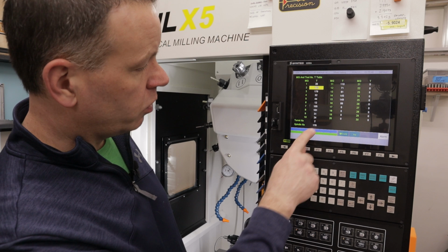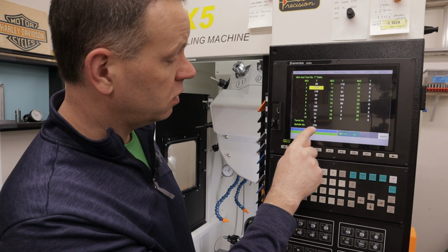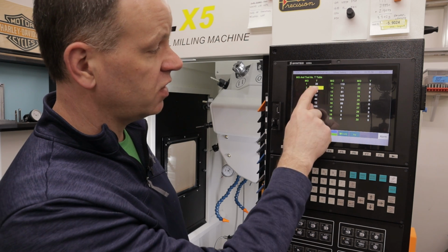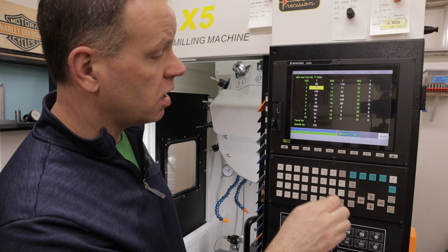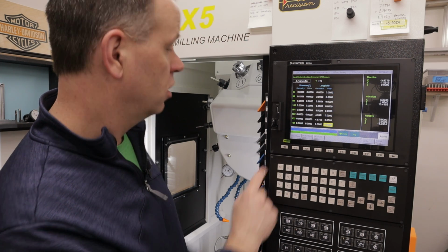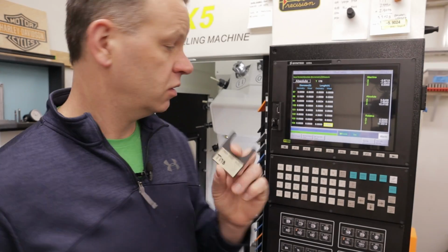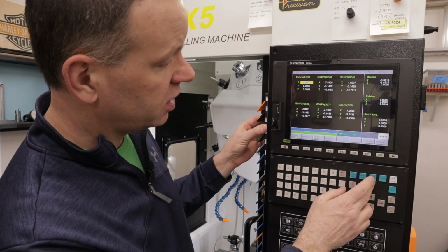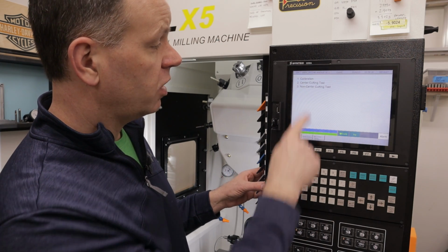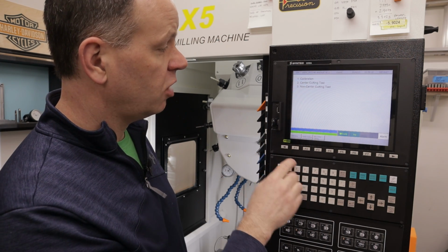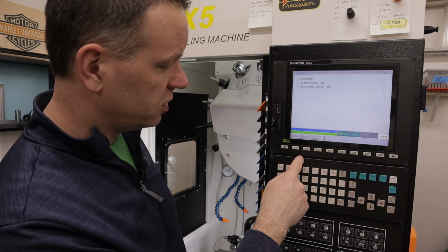So right now it tells you turret number 2, spindle tool 178. So that's the location we're at. That's what's in the spindle right now. So let's set that one since our number 2 was not set. Go back to settings, select tool setter. And we have 3 options: calibration, center cutting, or non-center cutting. And this is a drill, so it'd be center cutting.